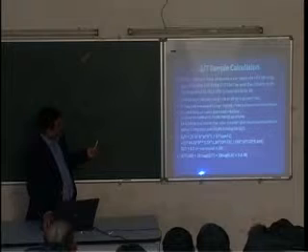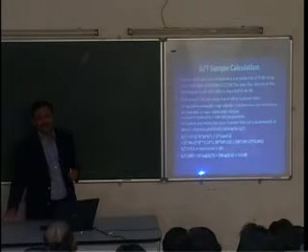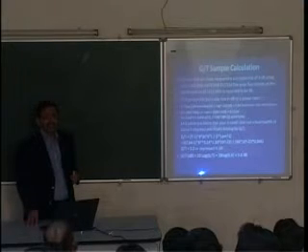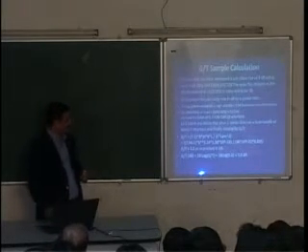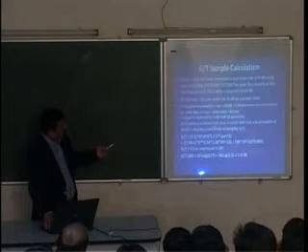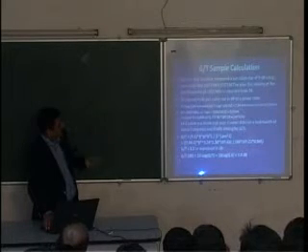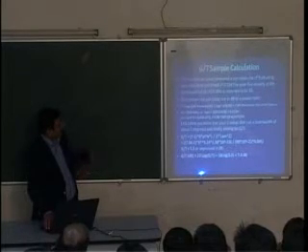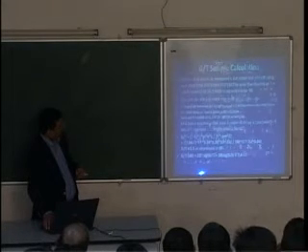So the idea was to give you a glimpse: we always know the noise temperature of a device, like the noise temperature of a low noise amplifier. The noise temperature of an antenna is also very important, because that gives a figure of merit for you. So this is one calculation we carried out for one of our antennas which is working at 1.4 gigahertz, and we calculated the G by T.